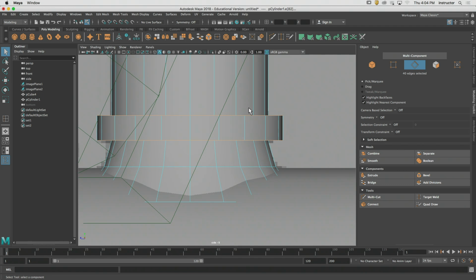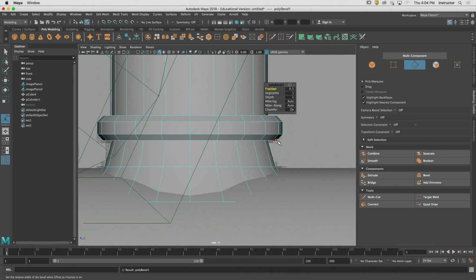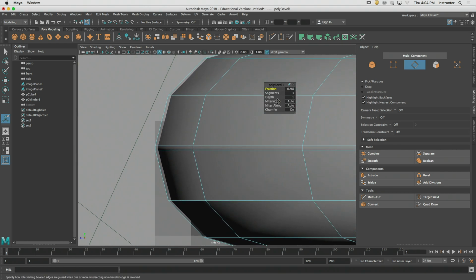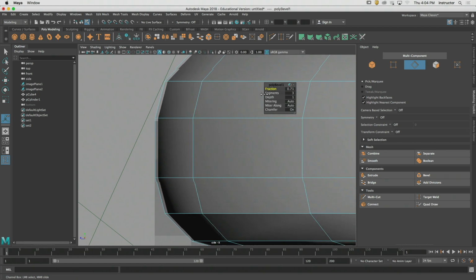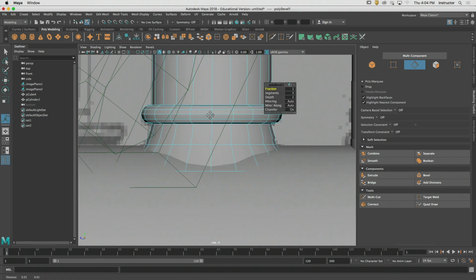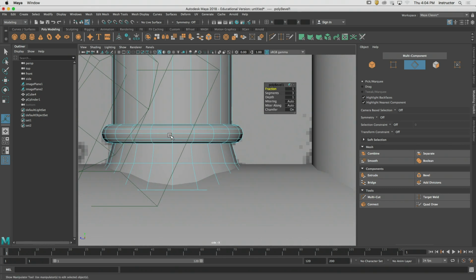It really is. But we need to define the boundaries first, which is why I squared it off with the idea that I'll just come back in after the fact and start doing this. Okay? So the Bevel tool is designed, let's just increase my segments here. There we go. Fraction, yeah. All right. And that's pretty good. You can even go all the way into the center like that. Oops, I'm sorry, I zoomed out too much. And now I have a pretty much perfect radius there.